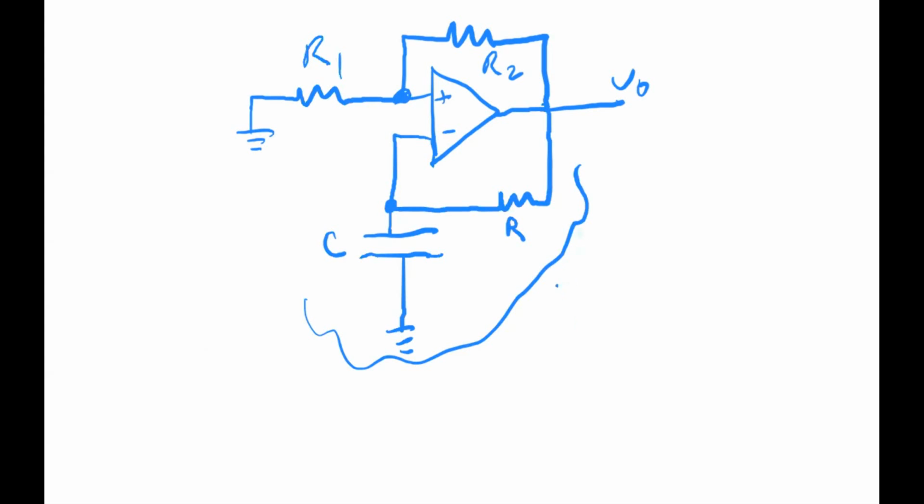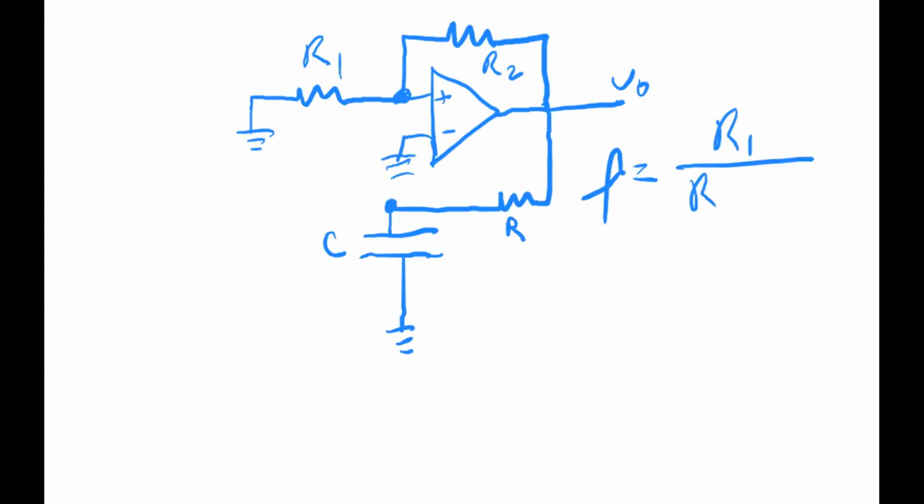So don't get confused by that, because the book defines a beta in this circuit for the bistable loop. That's the one where, if I disconnect the RC, we have ground here, and they define the beta as R1 over R1 plus R2. So if you're reading the book, that's how they're going to define beta, and I didn't want you to get confused in the context of the bistable loop, okay?